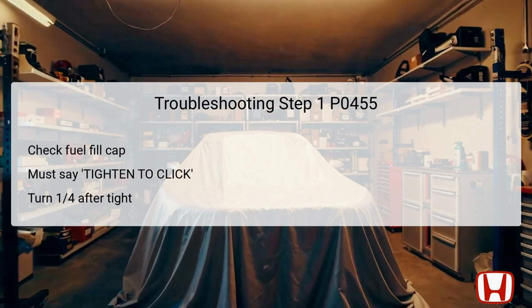The first troubleshooting step involves checking the fuel fill cap to ensure it is installed correctly. The fuel fill cap should clearly state "tighten to click" and must turn a quarter turn after it is primarily engaged to ensure a proper seal. A cap that is loose or improperly installed can lead to significant air leaks, triggering the P0455 code.